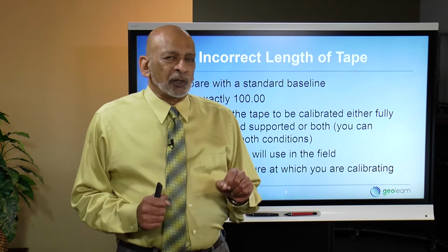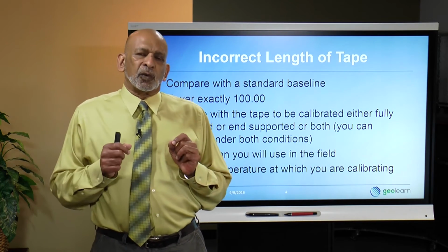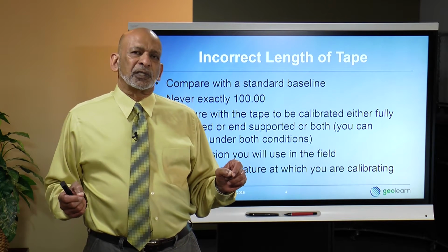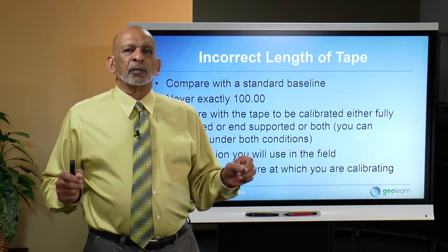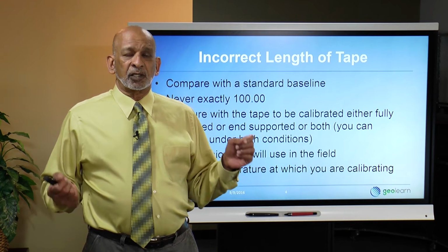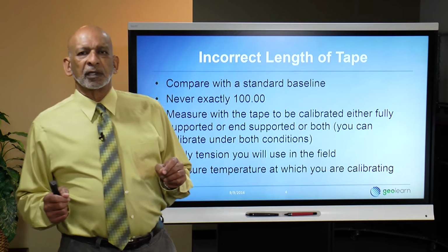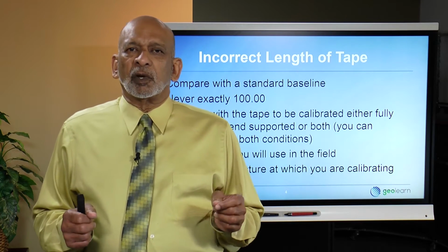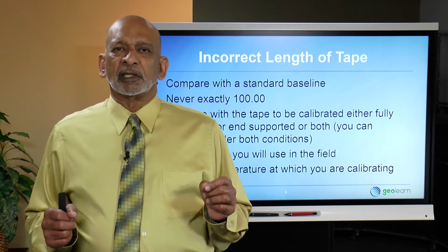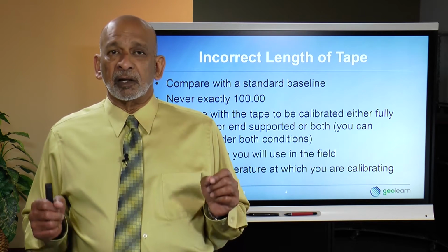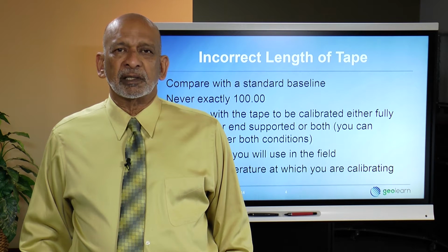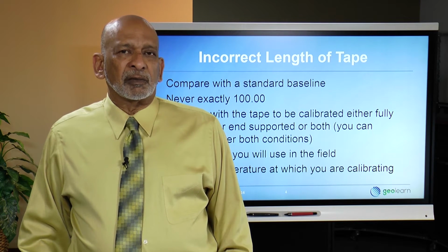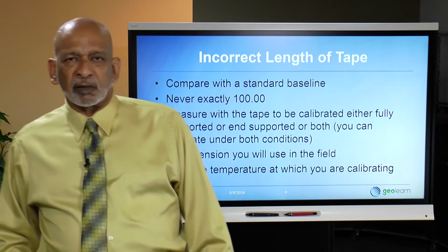Now, why are we doing this? Again, you may have this question. For those of you, especially with some exposure to surveying, it's very common to measure distances with either GPS or an electronic distance meter, often expressed as EDM. So why are we talking about taping? Well, there's a couple of reasons. GPS and EDM are not very accurate for really short distances. Surveyors just ignore this and don't even realize the impact of those errors in their measurements.